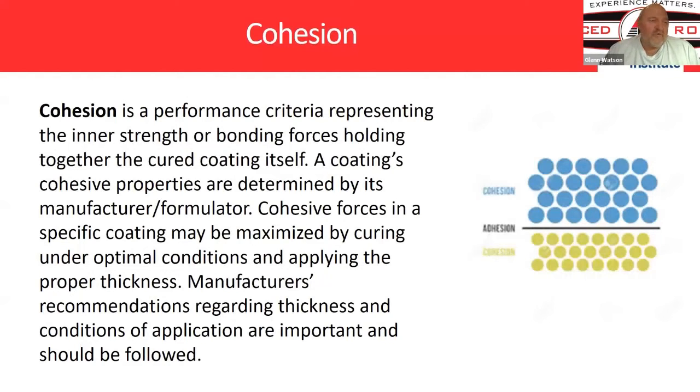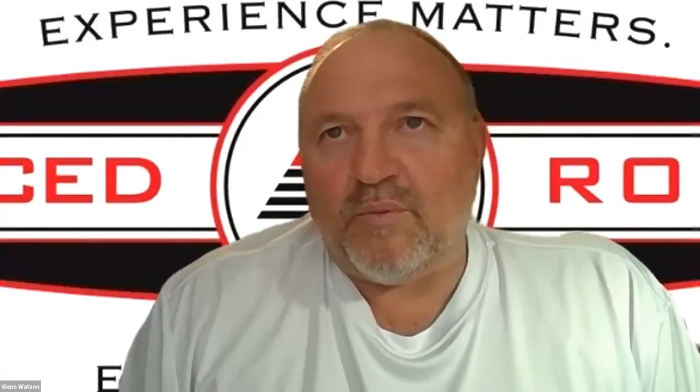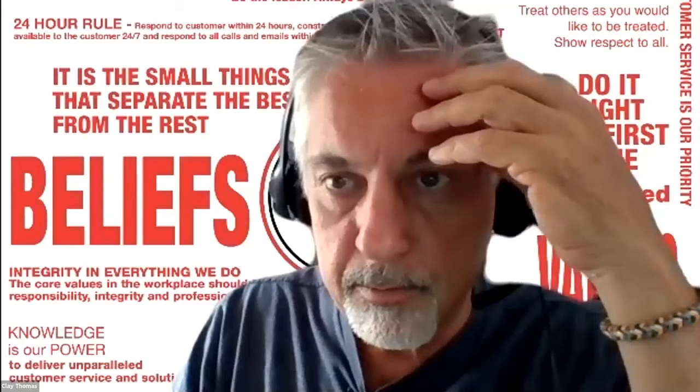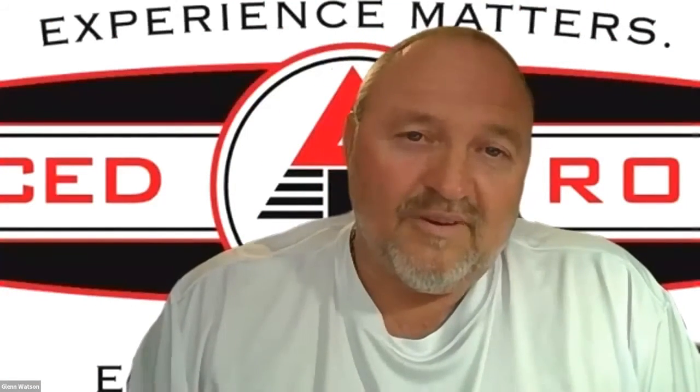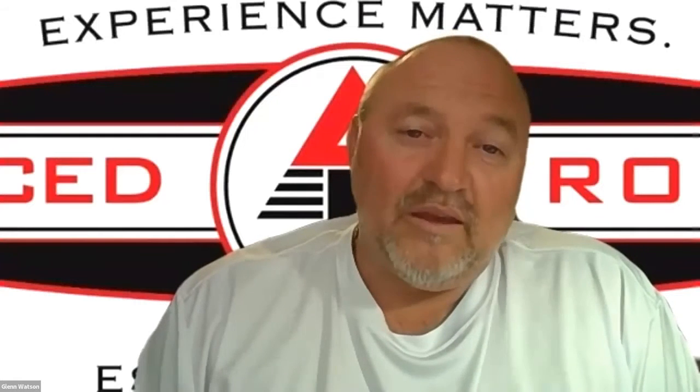Adhesion, as we said, was the ability of a product to stick to a surface. Cohesion is the ability for it to stick to itself. So you have adhesion, applying to a surface, and cohesion, how it exists within itself, how it sticks to itself. Cohesion is also a very important performance criteria. As we put these products down, a lot of times they're multi-phase. In other words, you have a base and a top, right? If you put the product down and it sticks great to the surface, then you put the second layer down and now it doesn't want to stick to itself, now we've got an issue. So adhesion and cohesion are sort of the same concept, but different.